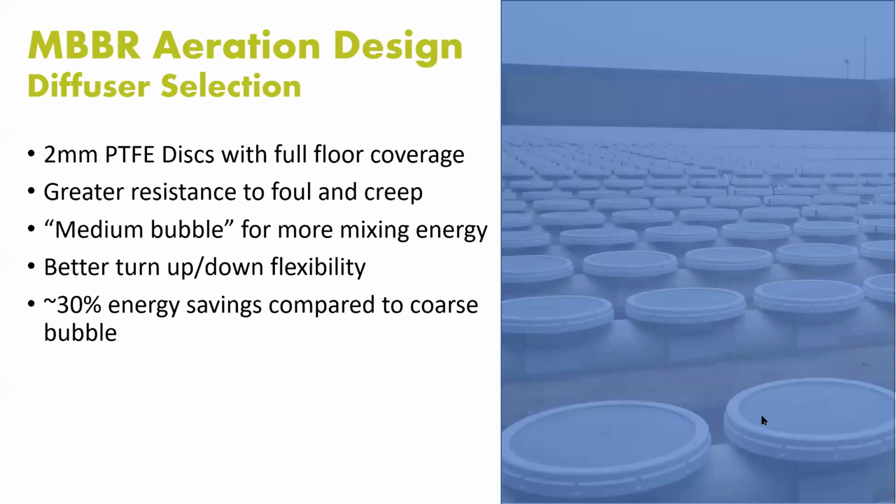That's why people like to use coarse bubble in the past. Now that we have PTFE, we have this greater resistance to foul, we have greater resistance to creep. We have many instances, we can talk about it more in our SSI aeration webinars, where operators are able to go 5+ years without having to drain the tanks to do any maintenance on those membranes.